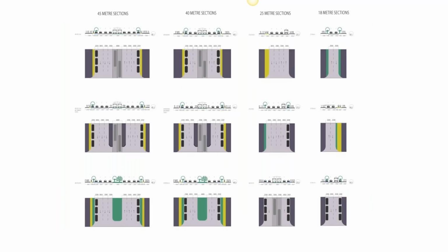And we extend it also to our street networks. In the beginning we may just be laying out center lines, but we determine what those primary roads look like, what those tertiary roads look like, secondary and quaternary, and even get into quintenary, I guess that's the word, the fifth level. So again, we do it by rules. We may have 3 or 4 different sections for a 45-meter road, and there are certain rules for what happens when that joins another 40-meter section.